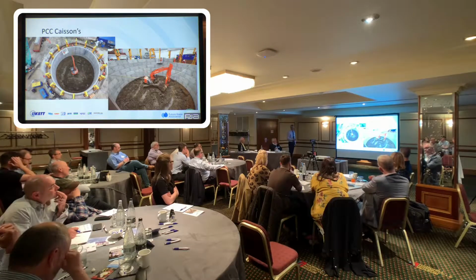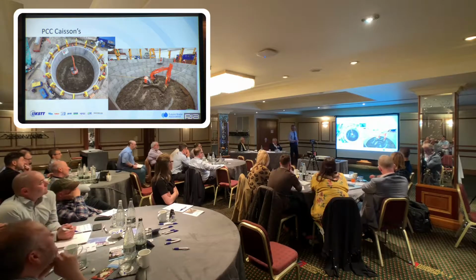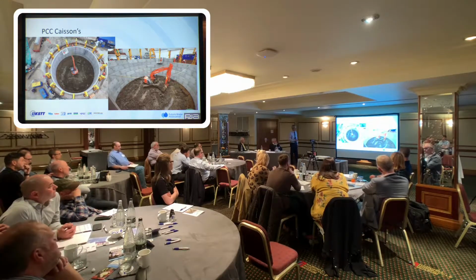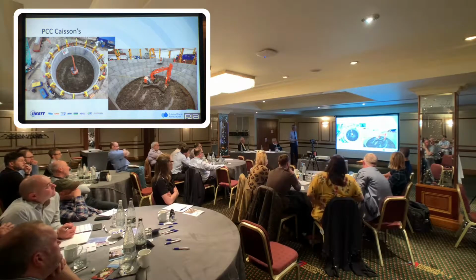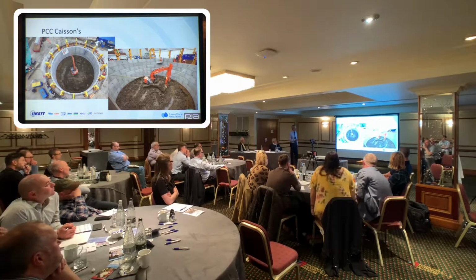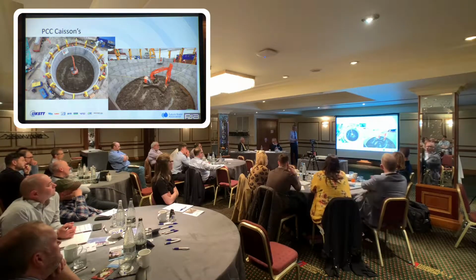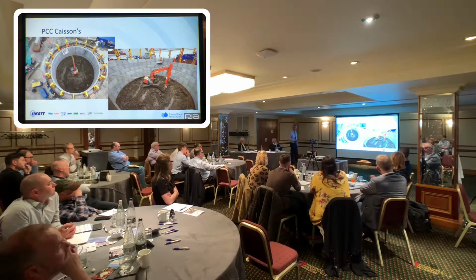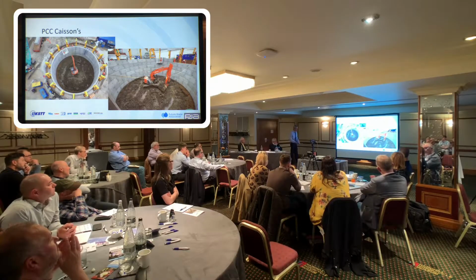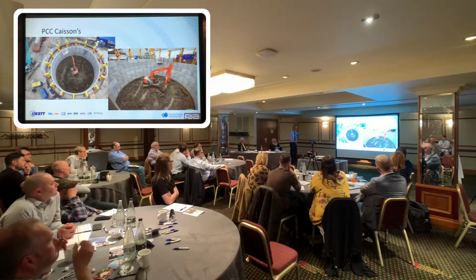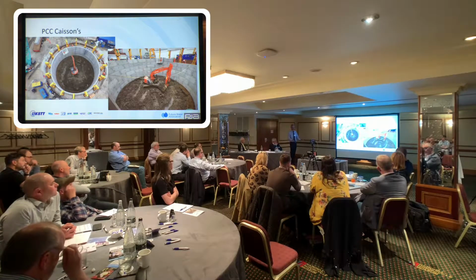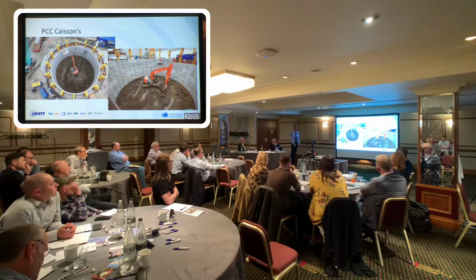So this is a couple of pictures of precast segmental shafts being sunk as caissons. So around the top here you've got a number of hydraulic rams. Each of these rams is capable of 50 tons of pressure to push down. But generally, they are used for steering the shaft more than they're used for actually jacking the shaft into the ground, especially in dry conditions.